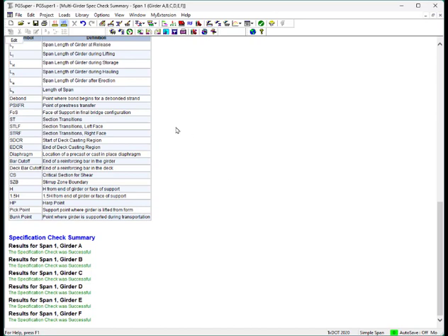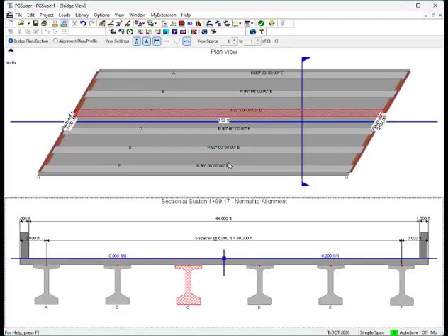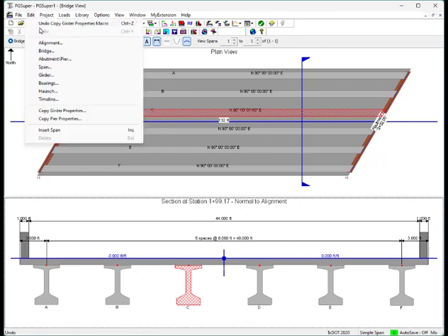There's no drainage on this bridge. How could we have missed that? Let's take a look. Oh, no. The bridge is flat. Okay, we have to make a last-minute geometry change here. So I'll go ahead and edit the alignment.